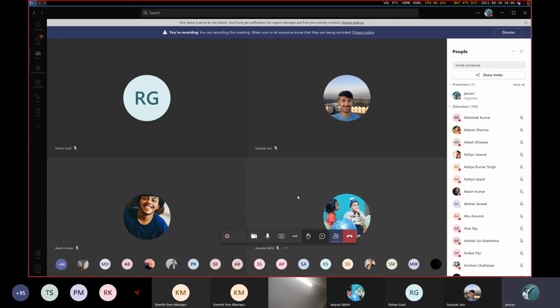Now, without going into too formal a definition, we will say that beams are the kind of members which are slender, so they are quite thin with respect to their length. Usually they have an unchanging cross section along their length, and usually when we talk about beams, we understand that the loading on the beams is taking place perpendicular to the longitudinal axis of the beam. So these are certain important things that we keep in mind when discussing beams.